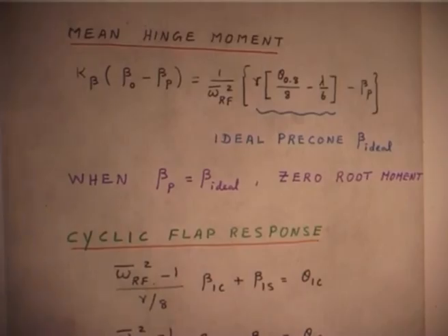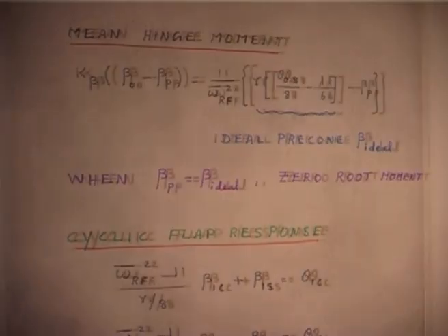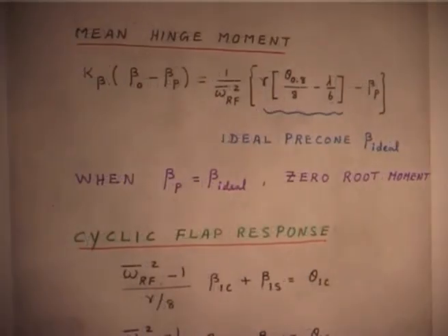That is the idea in actual design. What they do is they will keep a little bit of precone angle, so that you relieve, in the structural design, purely from a structural design point of view, you reduce the moment that comes at the blade root. Okay. Because these are all design features, plus they also have certain influence on the stability, because if you remember last class,